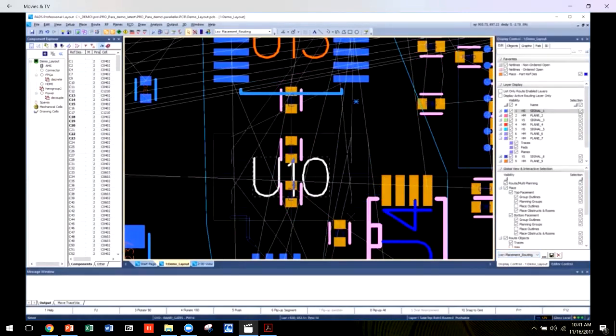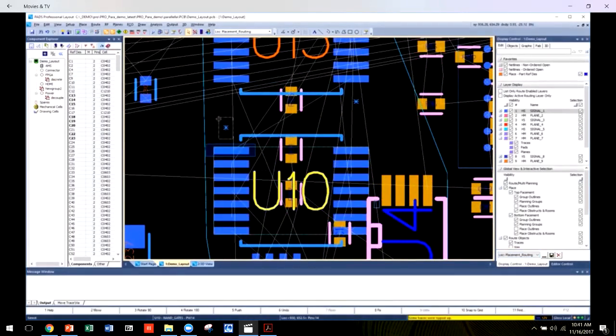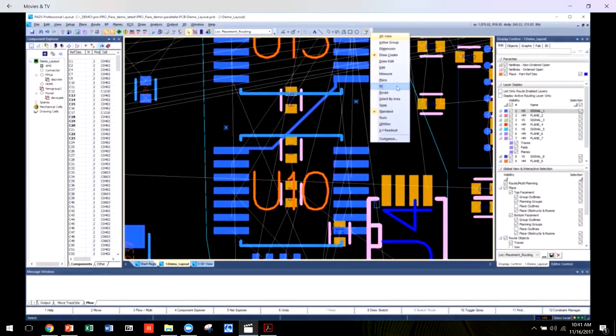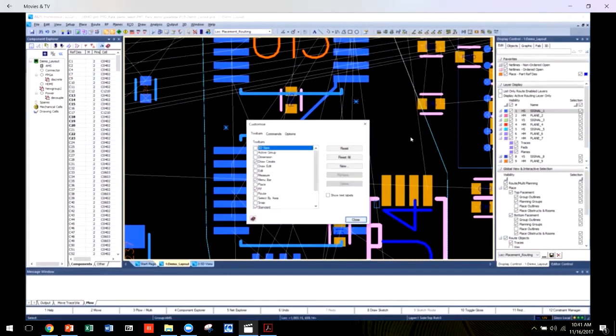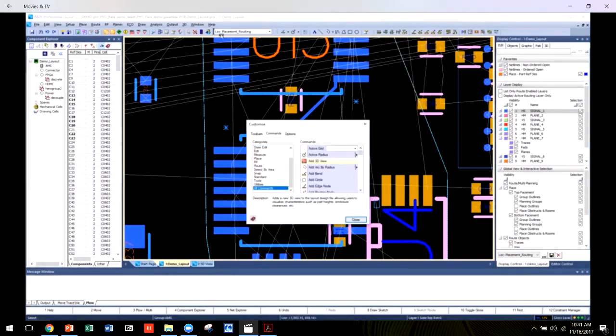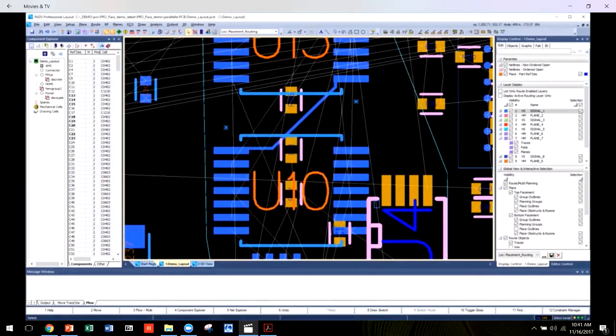In this example, enabling part reference designator and part pins, one can place and route without switching display schemes or commands. It's just a single click. By setting up your own toolbars, commands, and object visibility, you can personalize your environment to your heart's content, creating a highly intuitive, tailored environment for how you approach PCB layout.